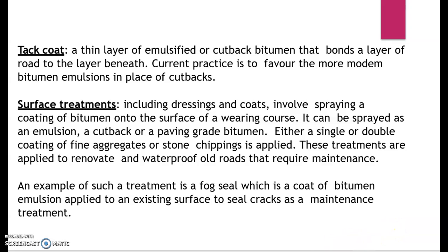The last application is surface treatments, which include dressings and coats involving spraying coatings of bitumen onto the surface of the wearing course. It can be spread as an emulsion, a cutback, or paving grade bitumen. Either a single or double coating of fine aggregates or stone chipping is applied. These treatments are applied to renovate and waterproof old roads that require maintenance.